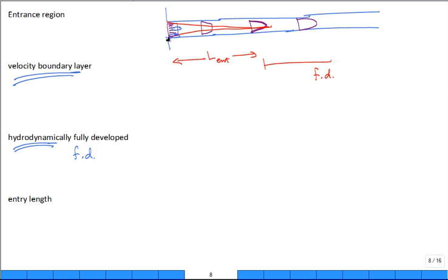Well, it has an effect on the profile of the flow in there. And so a lot of times when you have flow, this is entrance, but let's say I have a bend. Let's say it's a mitered bend. You know, ducts, a lot of times they'll do that. They'll just miter them together, and they put no turning vanes in there. Without turning vanes, you'll typically get a flow separation region right there when the flow is going this way.